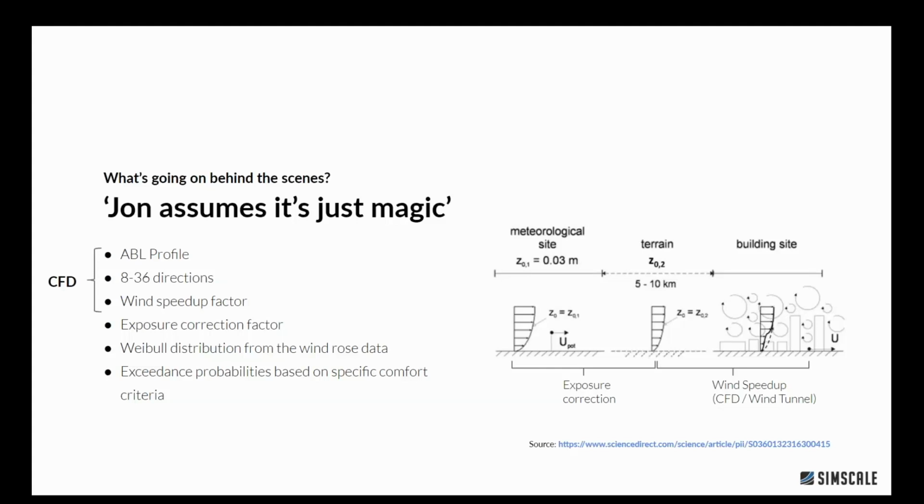So one other thing is that the wind data that we get is discrete. We have seen that there are velocity buckets from 0 to 2, from 2 to 4, and so on. To get actual probabilities correctly within the margins that we have, we basically smoothen this, or put the discrete data into a continuous probability distribution where you can then compute the actual exceedance probabilities.